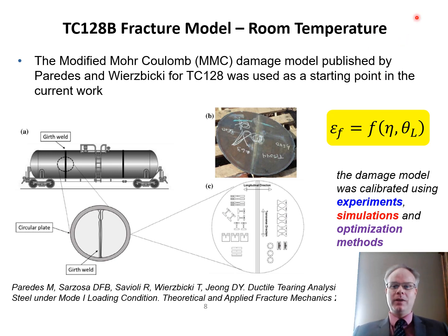So now what I'll talk about is the ductile fracture model. We're using the Modified Mohr Coulomb model. This model was published for room temperature and one strain rate, by Paredes and Wierzbicki. This model, without going into a lot of details, is a function of stress triaxiality and load angle.